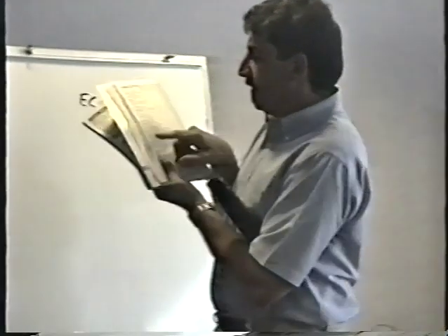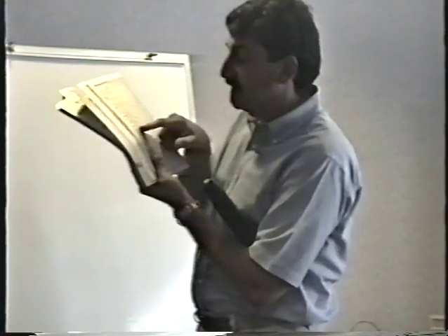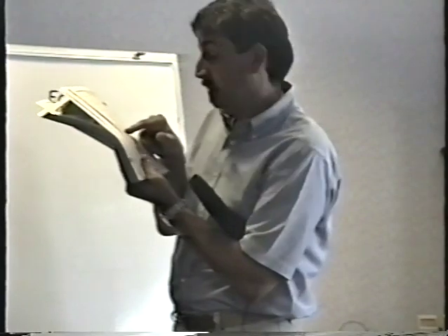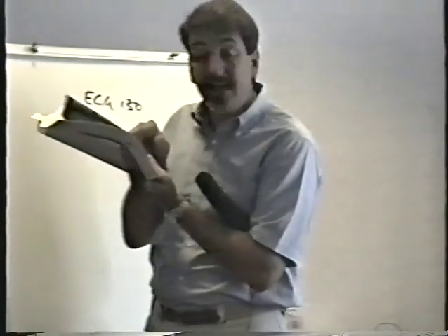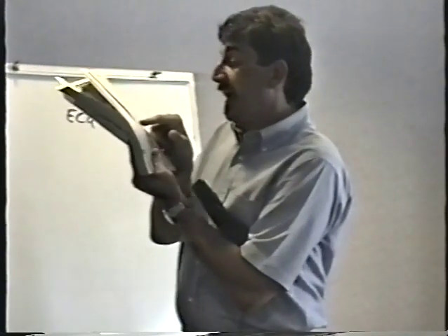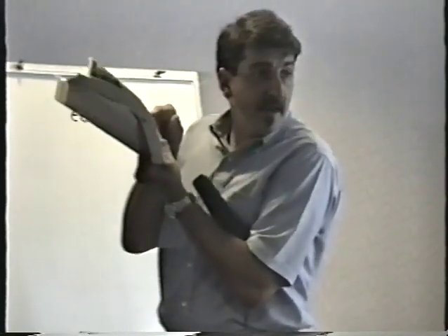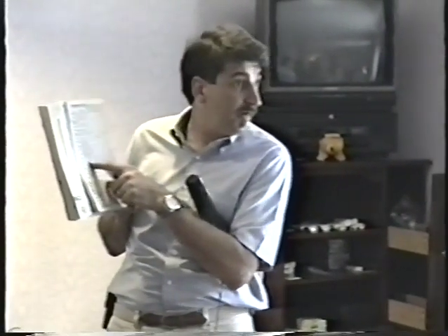And here it is right in the middle of the page, and it says ECG 130. What does it say about it? Well, it says it's an NPN transistor. It says it's made out of silicon, which it is. There's another type of material called germanium that we don't really use anymore. It says that it's commonly used as an audio frequency power amplifier, which it is. It may not be used like that in our case, but that's what it's commonly used for. It's complementary to an ECG 219. That means it's the same specs but opposite polarity.